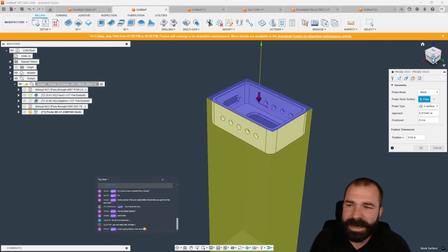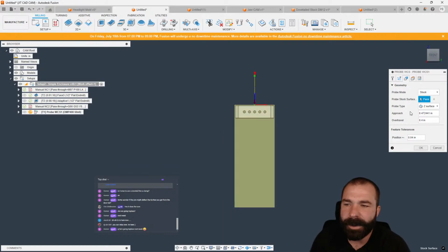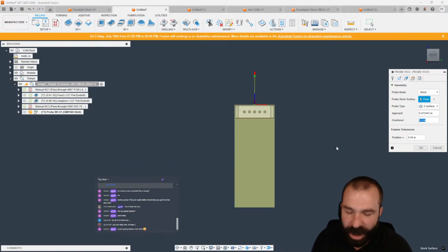Now, I do need to keep in mind that every time I go in and probe, once we run one, that variable has changed, right? So I am going to set my over travel a specific amount. Again, I don't know what this part depth is off the top of my head. Let's say it's 1 inch for convenience. And then we're going to run 4 of them. That's 4 inches. Maybe you have 50, 60 thou between them. Let's just chalk it up to giving this all the way down to 6 inches worth of over travel.